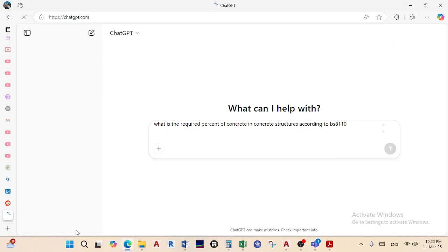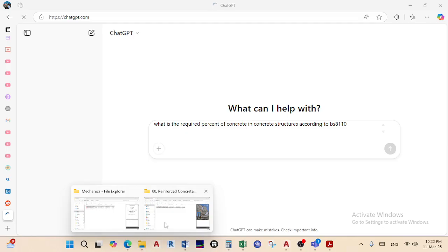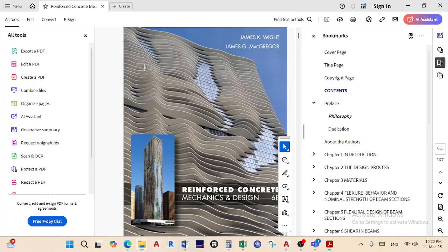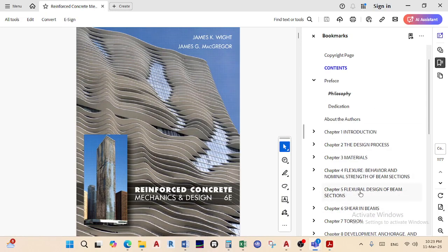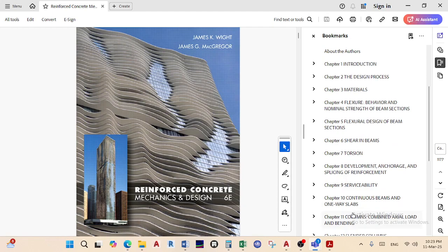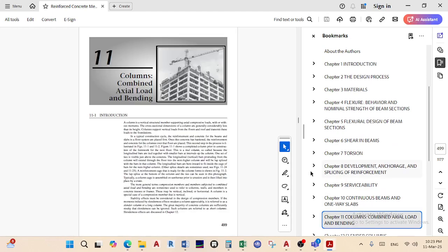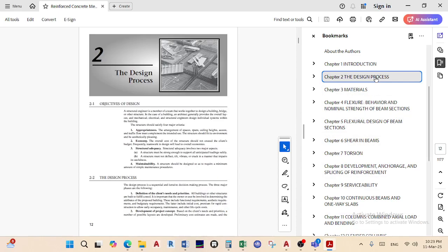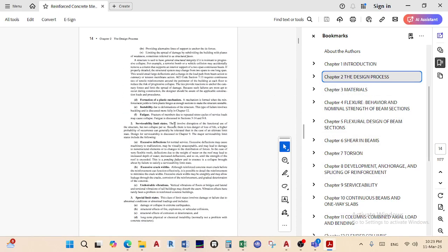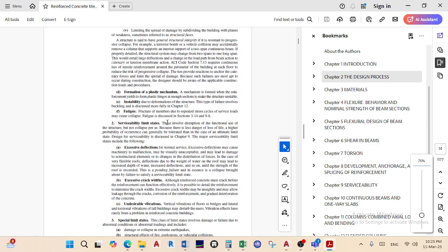So we have used 1.46 percentage of reinforcement to be able to achieve a reasonable utilization ratio. So why did we have to increase reinforcement? It's obviously because of the load that is active on this particular column. Same cross section, but more load, thereby requiring more percentage of reinforcement for it to have a reasonable utilization ratio.